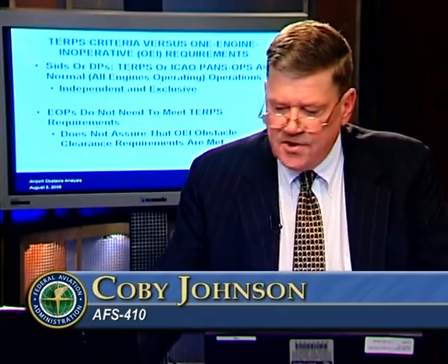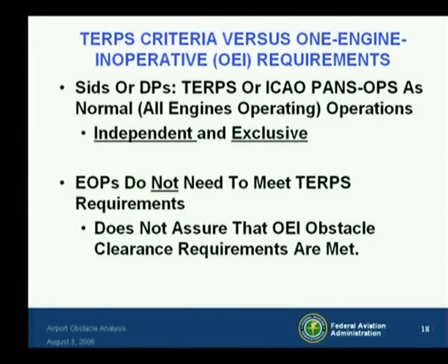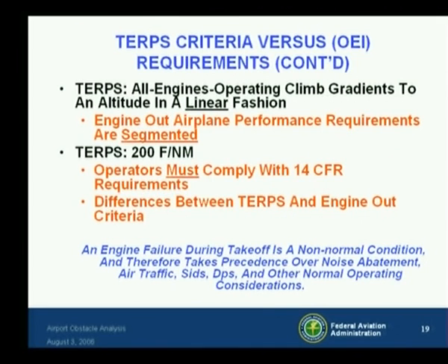With CFR performance criteria, SIDs, or departure procedures, are based on TERPS or ICAO PANS-OPS as normal all-engines operating operations, period. Thus, one engine inoperative obstacle clearance requirements and the all-engines operating TERPS requirements are independent and exclusive. EOPs, engine out procedures, do not need to meet TERPS requirements. Furthermore, compliance with TERPS all engines operating climb gradient requirements does not necessarily assure that the one engine inoperative obstacle clearance requirements are met.